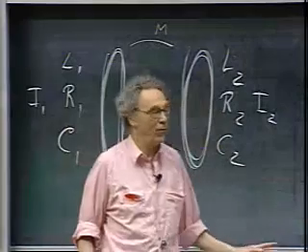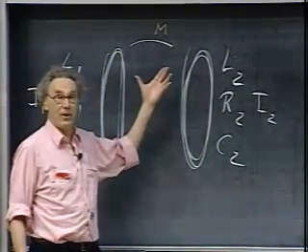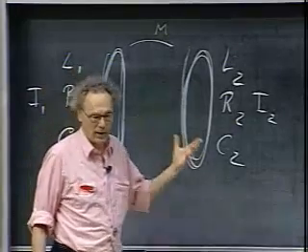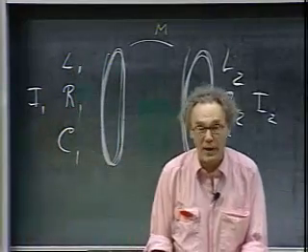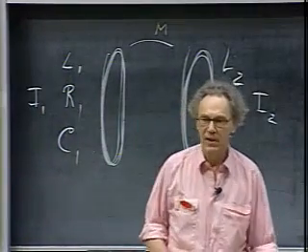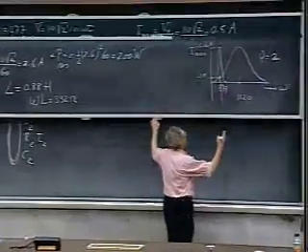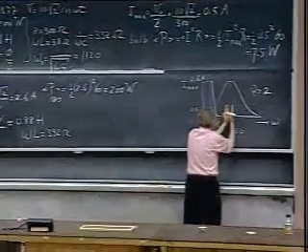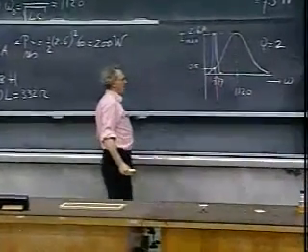Clearly, and very unfortunately, this never works for plastic bombs. You must have conducting material that you bring in, so it must be a metal. These systems have very high Q. Very high Q means they're extremely sensitive. If you have very high Q, that curve is extremely narrow, and so the slightest change in M, you go off resonance and you get your alarm.